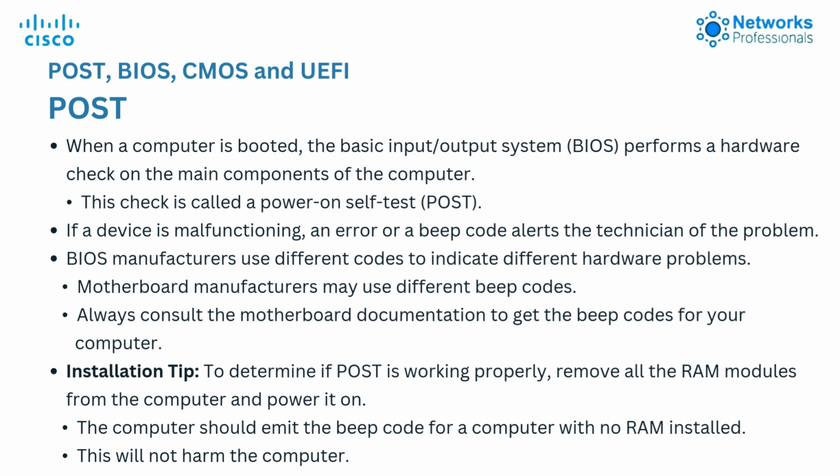Installation tip. To determine if POST is working properly, remove all the RAM modules from the computer and power it on. The computer should emit the beep code for a computer with no RAM installed. This will not harm the computer.